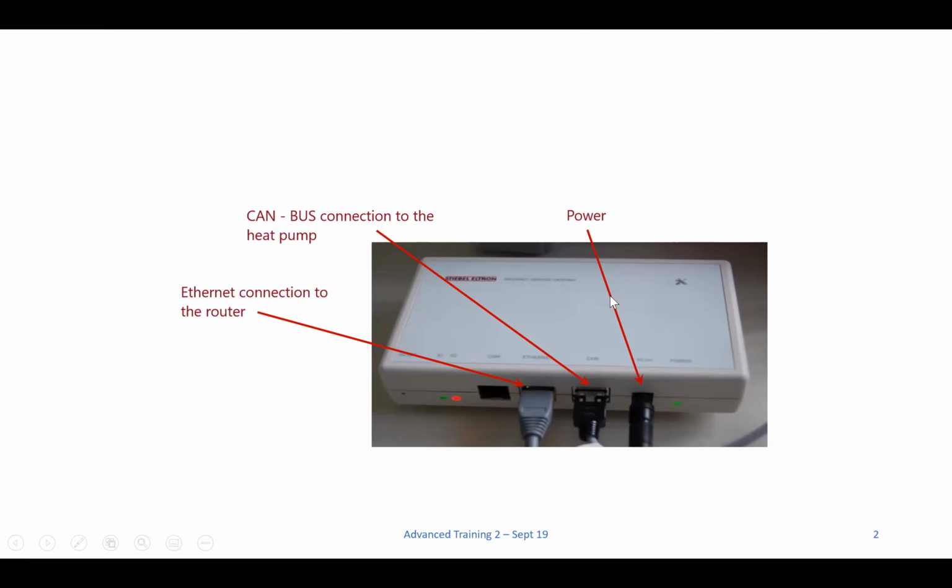So we would prefer the Ethernet being extended to the ISG, then the CAN bus from the ISG to the WPM being extended. It's just purely for data transfer reasons. We just want a nice, clean, reliable signal without dropouts. As you can imagine, ISG dropouts could be the cause for a service call, and that can be painful.